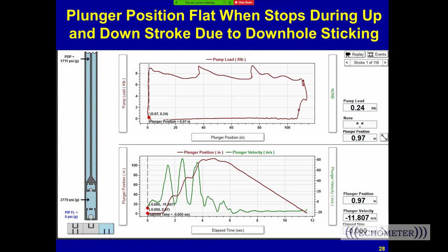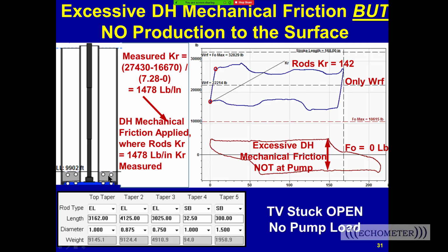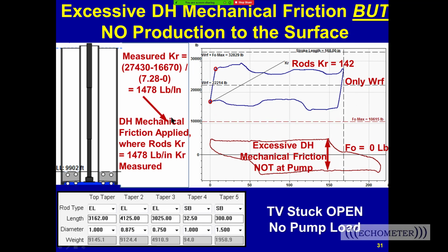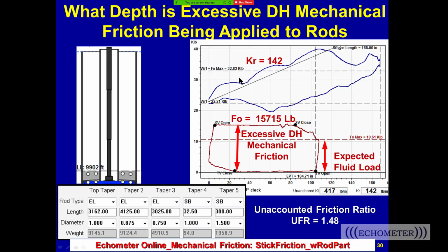Okay. Well, on slide number 33, if you can go there. There's a number of slides with similar content. Yeah, right there. Were those dyno cards collected using a PRT? That's a good question. Now let me go back. See this data right here. This is the same well acquired with the polished rod transducer.